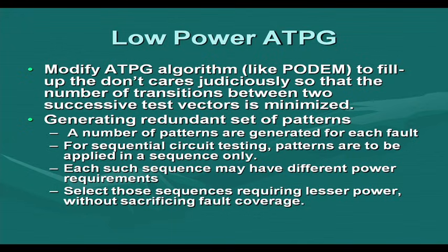So, there is a sequence of patterns doing the test excitation and observation. Each such sequence may have different power requirements. For the same fault I may get different sequences of test patterns, so there is an option of which sequence we pick.